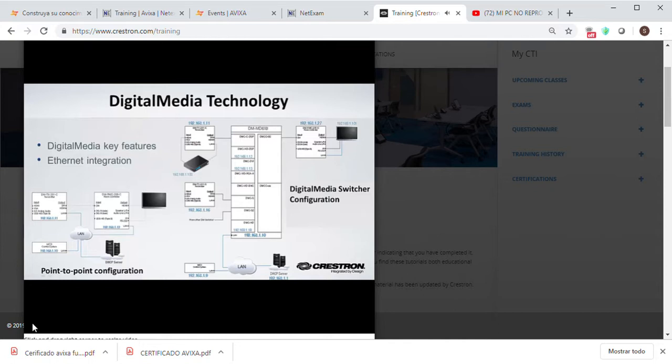For example, if a system contains a DM-TX200 and a DM-RMC100, the room controller must serve as the uplink point, since the DM-TX200 does not provide an Ethernet port. But if the DM-TX200 is replaced with the DM-TX100 or DM-TX300, the Ethernet uplink can occur at either the transmitter or the room controller, since both of these devices have an available Ethernet port. Note that in a point-to-point system, only one of the devices should connect to the main network. In systems with switchers, the switcher should be the only device connected to the network.